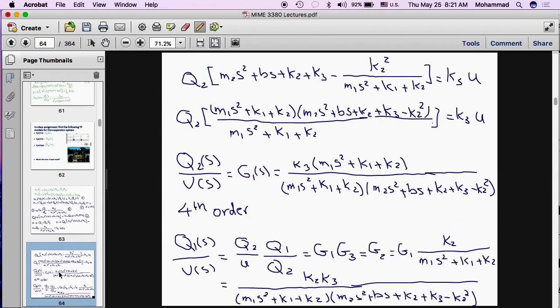Okay, and we could also find other models that we needed. So in this next slide, we found G1, which is the relationship between road roughness and the change in displacement of mass 2. That's G1(s). The benefit that the transfer function brought was to give you focus and ease of seeing relationships.